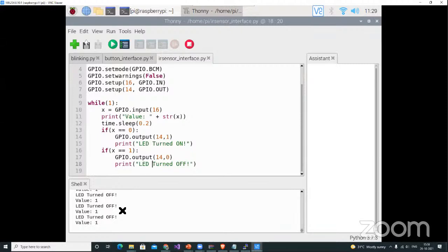Just a second. Turn on the video. So this is the IR sensor. Here you can see this is the IR sensor. This is the black surface, guys. The chair I'm using is the black surface, so it will absorb all the infrared rays. The white LED is the transmitter, and black is the receiver. It is the black chair, so it just absorbs everything.